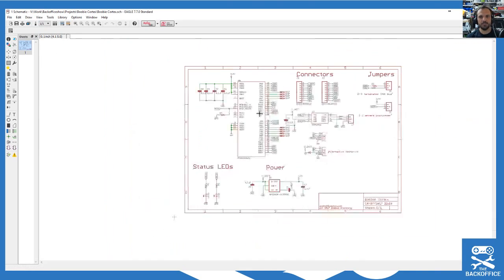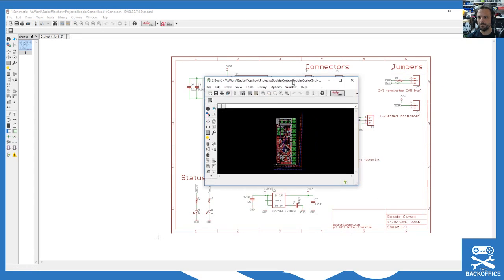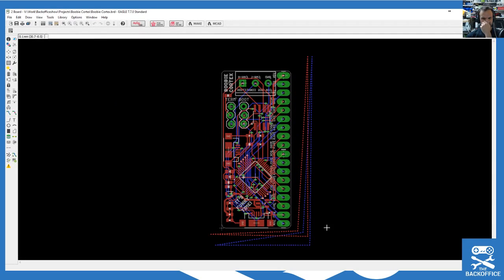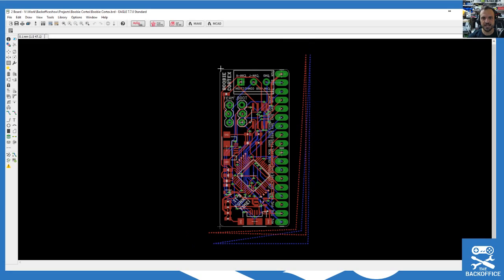So the PCB is basically laid out. I spent a couple of hours and got that done. But my main area of concern is the board layout. And Tilo, look what I've been doing. I've been doing the ground plane. But as we know, inside Eagle, it always helps to shift the ground plane off the board until you've finished your auto routing. Otherwise, it's going to totally freak out.